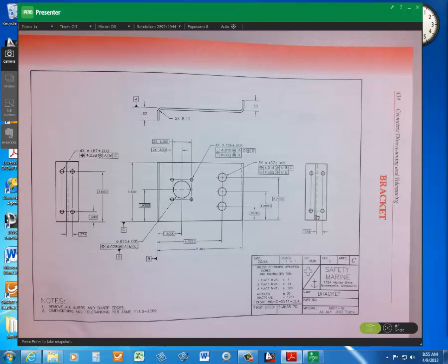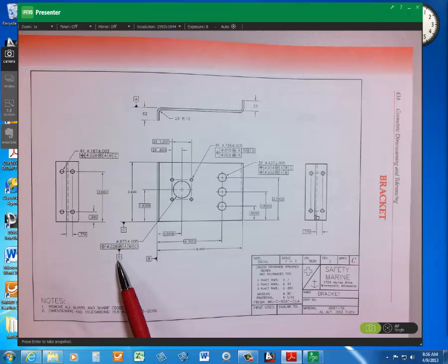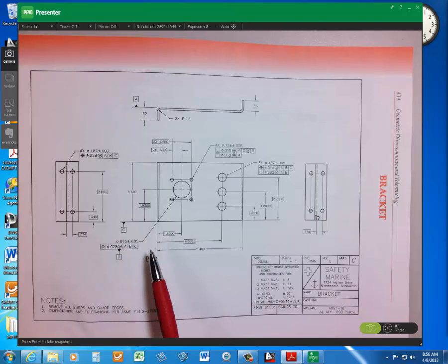So looking at the 0.875 diameter. That's a true position tolerance. Got the little symbol there. Positional tolerance is 0.028. And datum D then would be this description. Okay, it's an axis datum, because it's attached to this, which is a diameter. So it is an axis datum, which is the 0.875 diameter. That's basically how you would describe it.